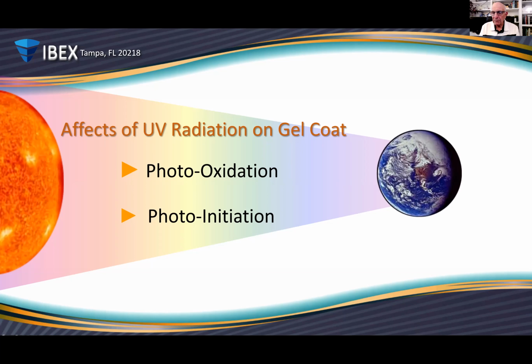The bottom line with this whole thing goes back to how critical was the application of the gel coat and the curing of the material. If your application is correct and it's properly cured, it performs better under this UV exposure than it might not be otherwise.